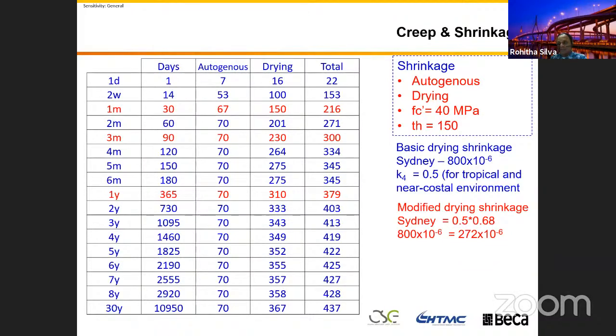I have this saying all the time. When I was reviewing some designs, especially segmental box girder constructions, the designers said, okay, we are moving massive gantries, we move this gantry in 3 weeks' time to there, we cast the box 1 week before, bring it here and place it, and my creep and shrinkage is happening from 28 days to 30 years.